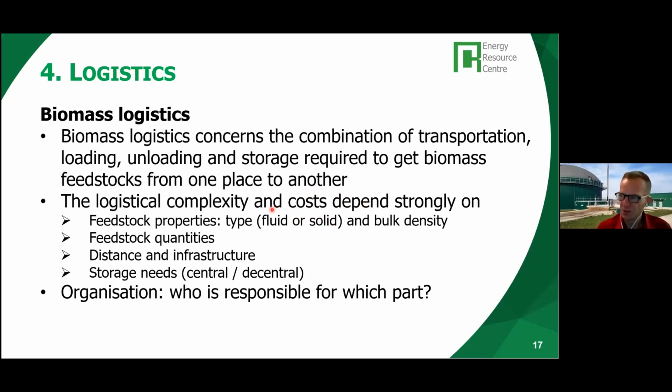So whether it's fluid or solid type of feedstock, and the bulk density, the amounts, of course, the feedstock quantities, the distance that needs to be covered, and the status of the infrastructure, the roads, in some cases rail or even waterways can be considered, and the storage needs in order to assure a continuous supply of biomass, whether that is best done centralized, so near the power plant, or whether it's best done decentralized, so at the place where it is being produced.